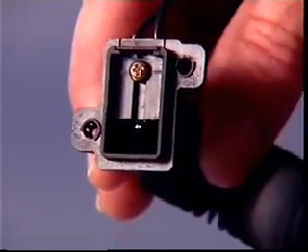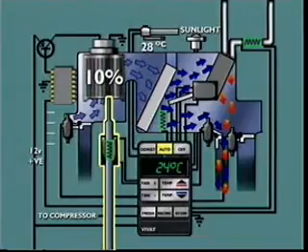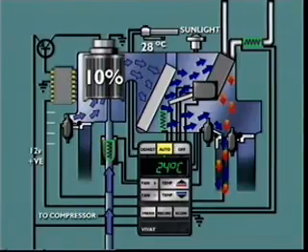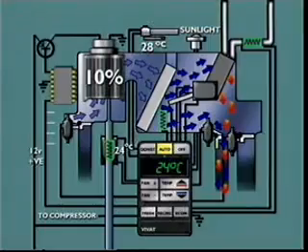The cabin air temperature sensor is mounted in a tube-type device called an aspirator. One end of the tube is open to cabin air, and the other is connected to the interior fan. Operation of the interior fan creates a flow of air through the aspirator. The temperature of the cabin air flowing through the aspirator controls the signal sent to the electronic control unit. The evaporator temperature sensor is located in the airstream, where the air leaves the evaporator and signals to the control unit the temperature of the air.